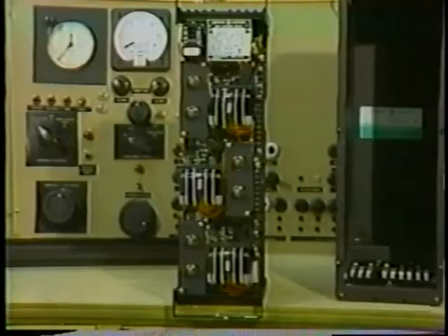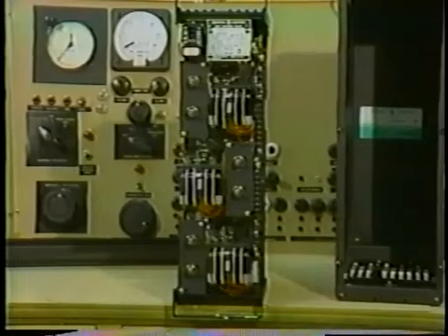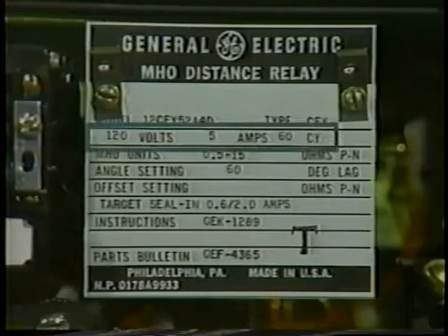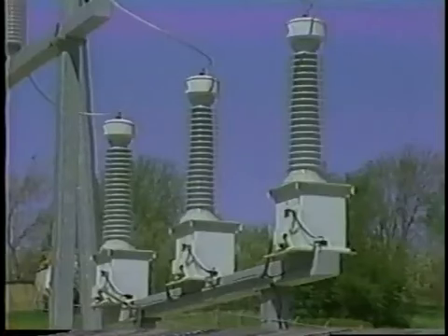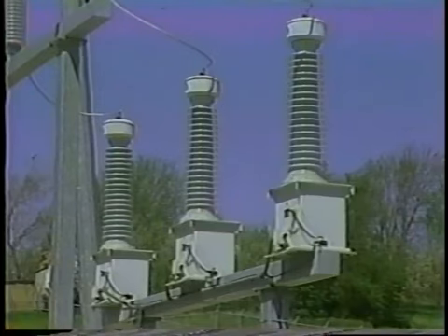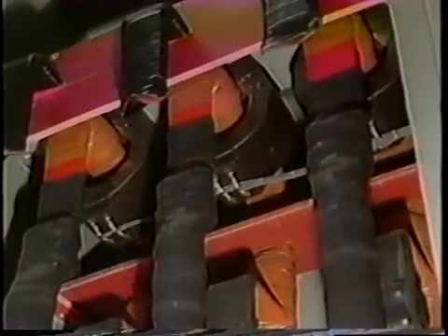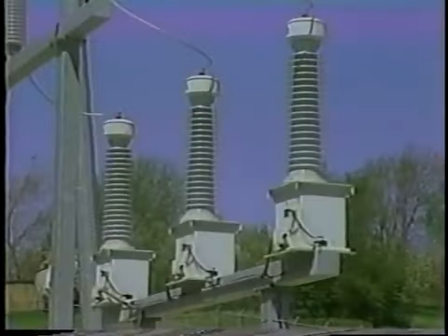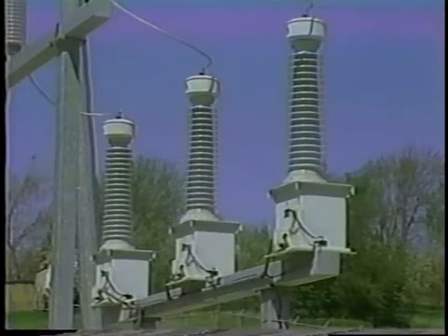Low voltage and current also permit the relay equipment to be made small and precise. Typically, the relay will work at, say, 5 amps and 120 volts. The instrument transformers are a critical component of the protection system, and consequently, they must be accurate. It's vital that the voltage and current provided to the relay from the transformers be a true representation of the current flowing or voltage level at a specific location. As we'll find out later, this may not always be the case.